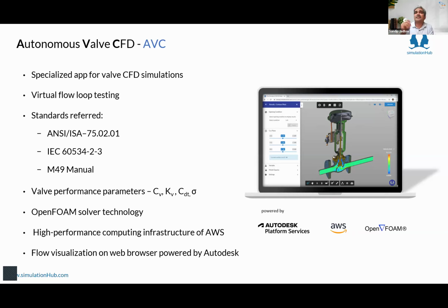So there is that kind of value. If you change a certain parameter, let's say you change a surface roughness parameter, you will get a different outcome. These design parameters are what you play with, and that matters a lot. I just wanted to bring that difference, because many times it looks like it's automated CFD. It's not automated, it's autonomous. And the big part is intelligence. Actually, how to create this computational model is the real 90% of the game in this business. So I just wanted to highlight that.